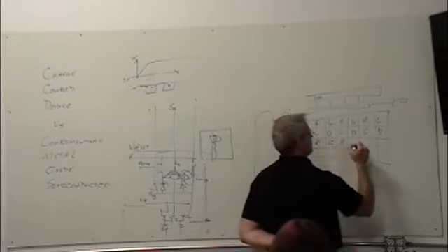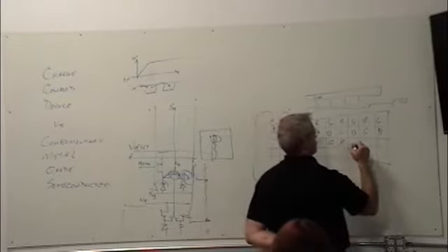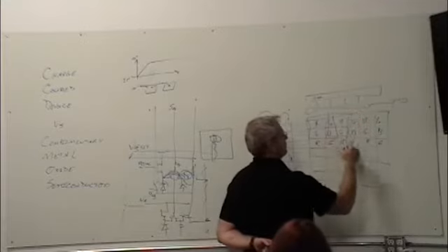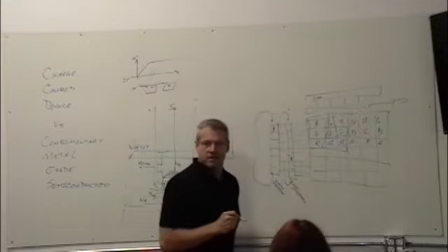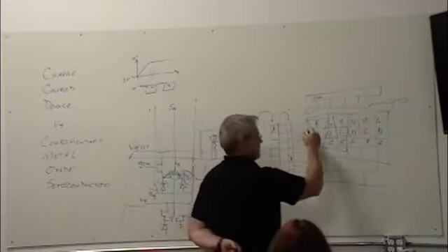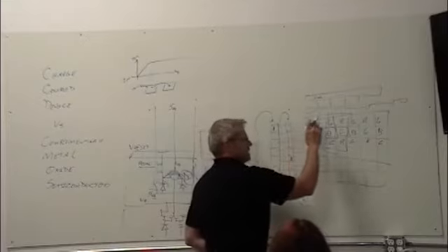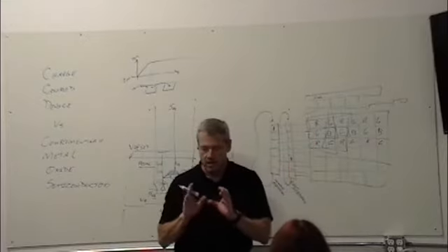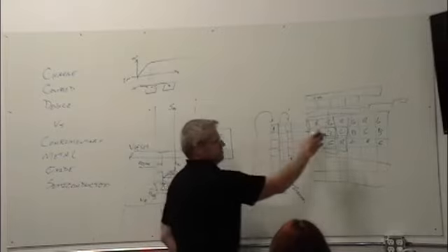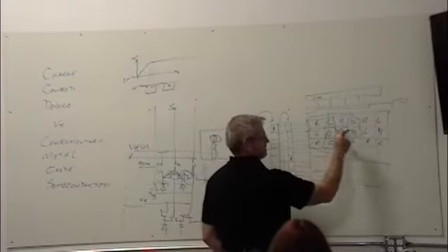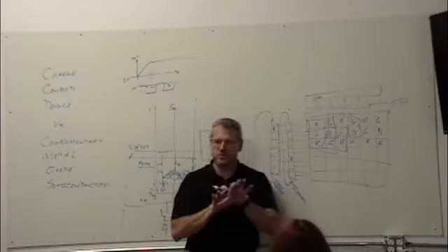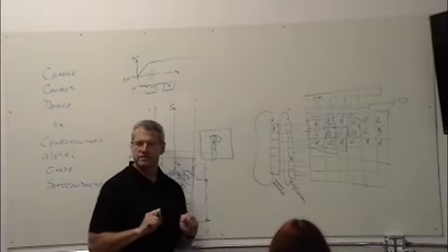Red, green, red, green. Now I've got red. If I look there, I've got red, green, blue. If I look there, I've got red, green, blue. So now I can play a game where I can do subframe sampling type things. This happens with CCDs also. Instead of saying this is a pixel and that's a pixel, I can dither back and forth and do some image processing and give a sharpened image.